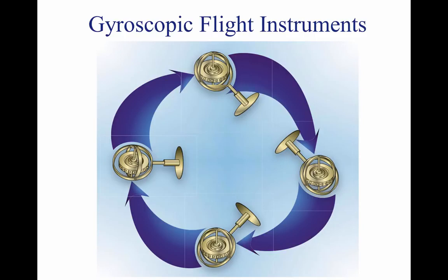There are 2 fundamental properties of gyroscopic action: rigidity in space, and precession. Rigidity in space refers to the principle that a gyroscope remains in a fixed position in the plane in which it is spinning. An example of rigidity in space is that of a bicycle wheel. As the bicycle wheels increase speed, they become more and more stable in their plane of rotation. This is why a bicycle is very unstable and very maneuverable at low speeds, and very stable and less maneuverable at higher speeds.